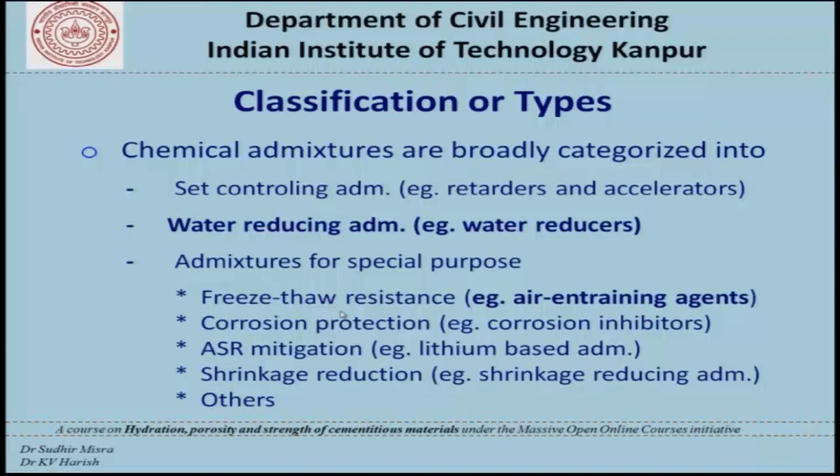For freeze thaw resistance we use air entraining agents or air entrainers. For corrosion protection we use corrosion inhibitors. For alkali silica reaction mitigation we use lithium based admixtures, and for shrinkage reduction we use shrinkage reducing admixtures.